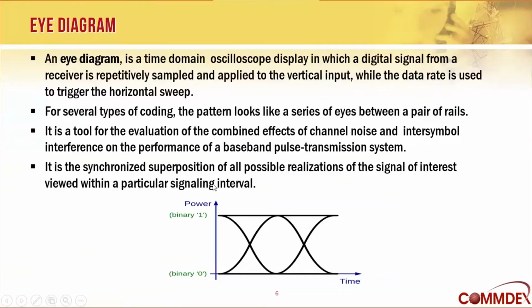We also have a tool called an eye diagram, whereas the constellation is a complex domain in I and Q, the eye diagram is a time domain diagram that we can present on an oscilloscope, where we actually show the signal in the time domain, and where we have the overlapping ones and zeros that create an eye-shaped image in the middle.